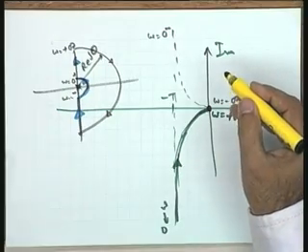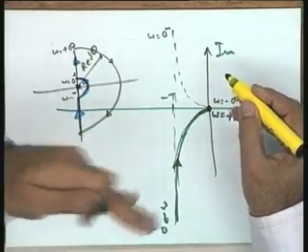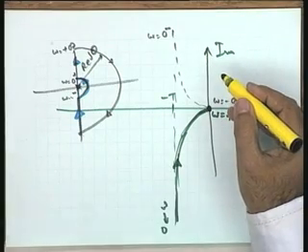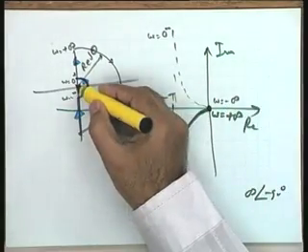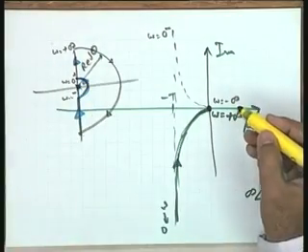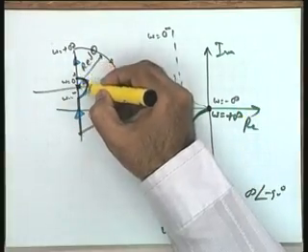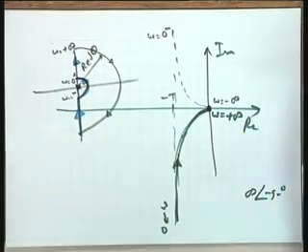In a real life physical system, a pole at s equal to 0 is an idealization of the physical situation. There will be some positive damping present in the system. Actually, this pole will be close to 0 in the left half of the s plane, and therefore I can detour it by taking a small semicircle with epsilon tends to 0.